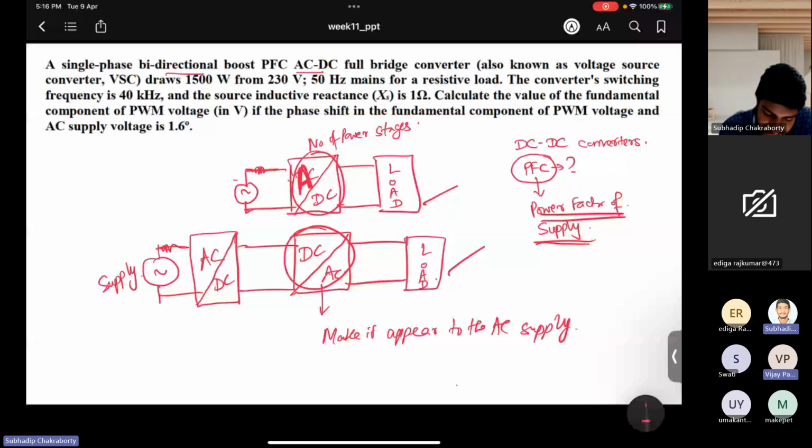Otherwise, what will happen if the RMS value of the current drawn from the supply is more, in case of non-unity power factor? Then I_RMS squared times R of the feeder or line will also be more. So you have more heat and more loss. So who will pay for that loss? The user is not going to pay for that loss, because of how the reactive power looks.